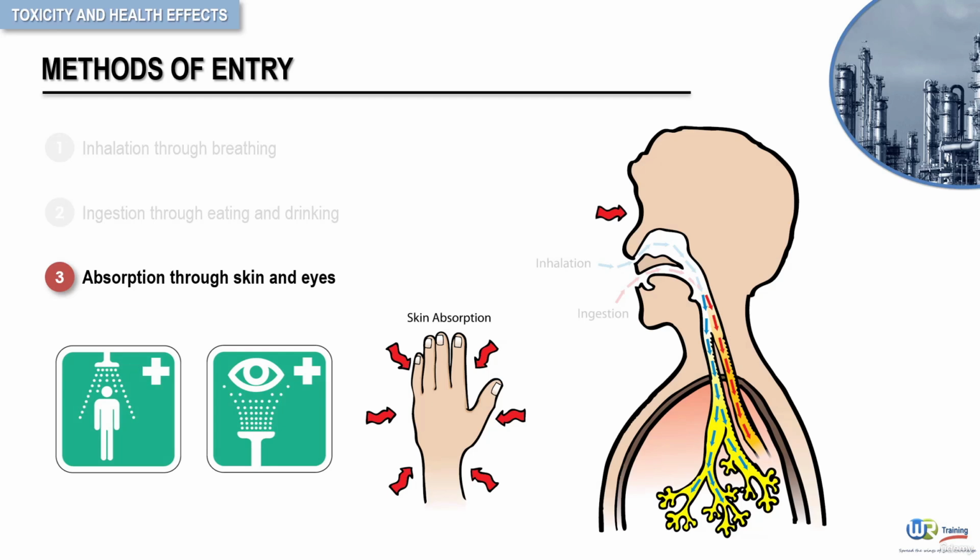Use a safety shower and eye wash when you come in contact with or are accidentally splashed with hazardous materials. Always use adequate engineering controls, administrative controls, and wear appropriate PPE to minimize exposure to hazardous materials. Avoid skin contact with hazardous materials, solvents, and any products containing solvents by wearing suitable protective clothing when necessary. And remember to report any defective equipment. If work clothing become drenched or saturated with solvents, they will act as a reservoir to bathe the body continually with the harmful materials. So keep in mind to remove and change work clothing or PPE promptly when they become drenched or soaked with harmful materials.